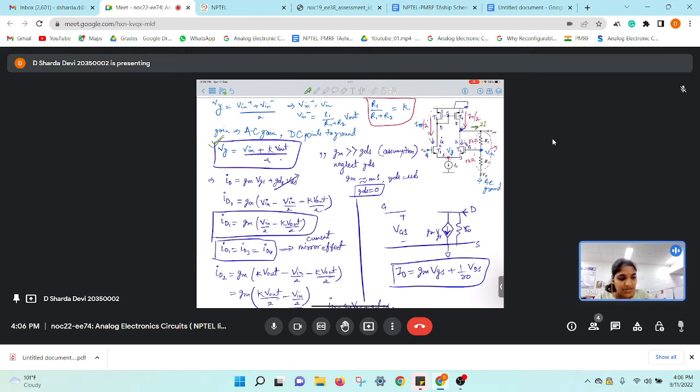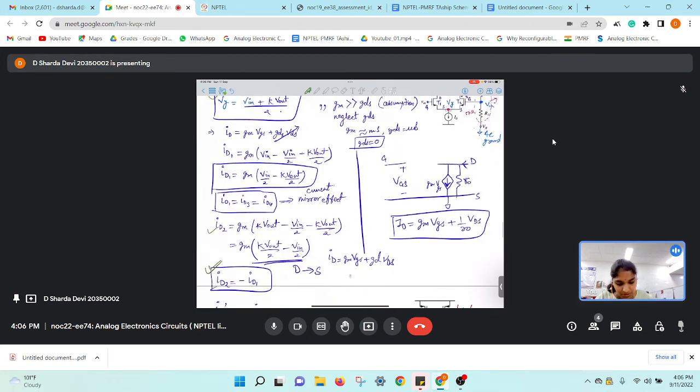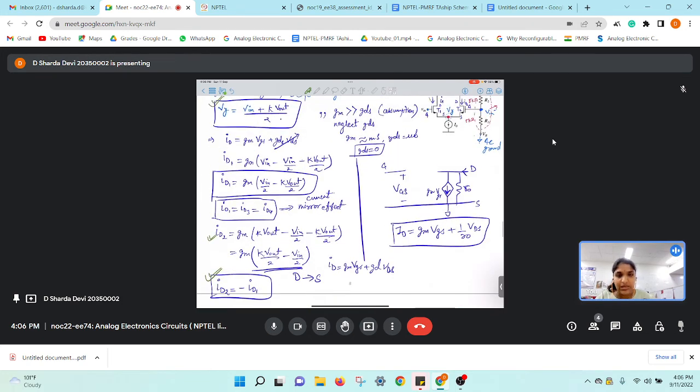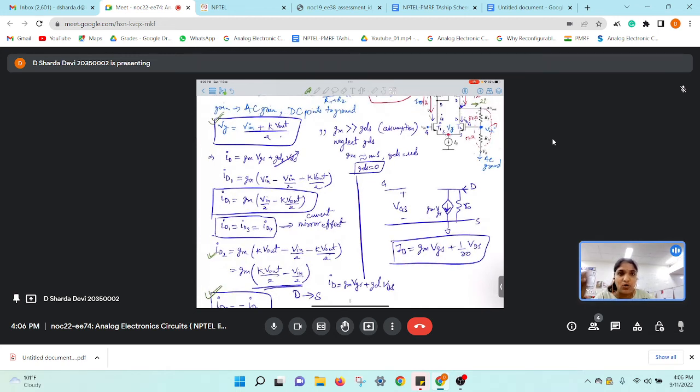So one component of current comes from the top PMOS and the other component comes from the bottom NMOS. From the expression that we got, the current's direction was opposite, from the output node to the tail transistor. But we wanted the opposite, so I simply added a negative to change the sign of it.